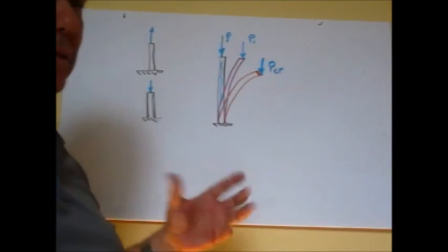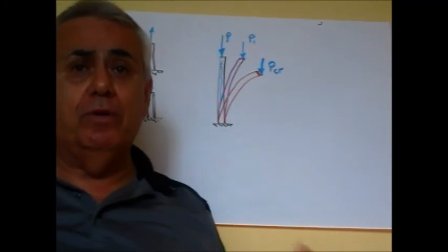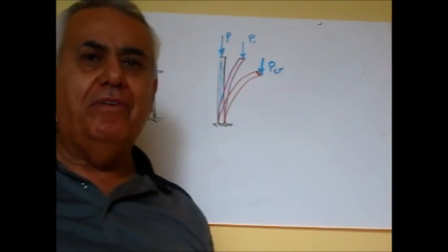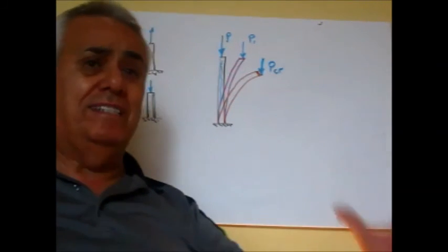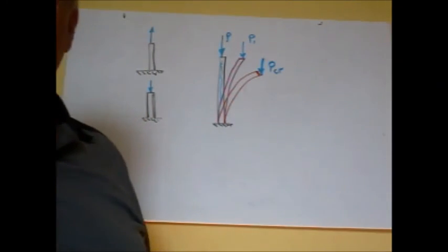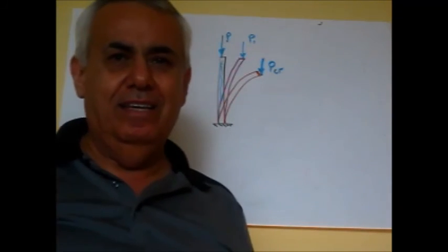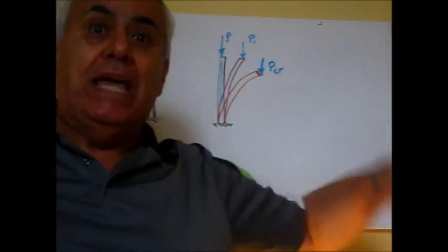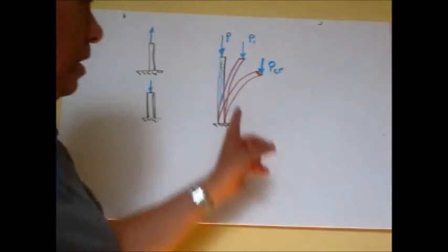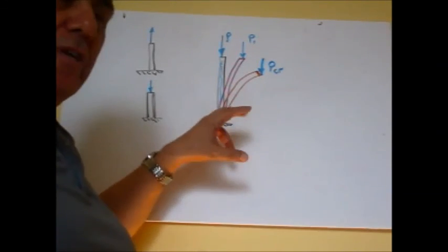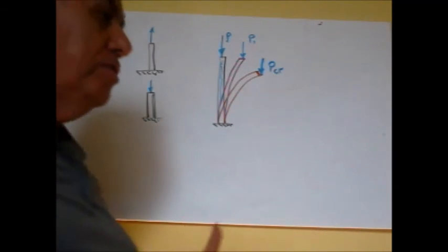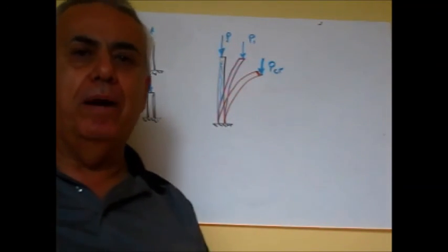The problem of stability was first addressed by Euler. The problem of Euler you are going to have in the lecture. That's all you have to know. You should never confuse these concepts. Unfortunately, I see people in everyday life, engineers, professionals, say it's going to break, it's going to lose the stability. You cannot say that. It's like saying an elephant has wings. Only in Disney cartoons. If you lose stability, you lose the equilibrium. If you lose the rigidity, there are too many elastic deformations. And of course, if you lose strength, it's breaking or having permanent deformation.